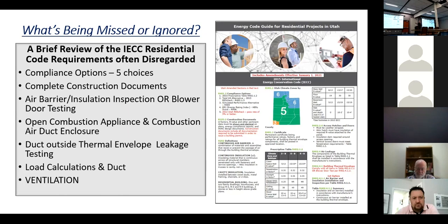Ridge vent doesn't fix it because ridge vent doesn't let a lot of air out. Turtlebacks, an 11-inch turtleback has a free area, by the time they put the screen and everything in it, somewhere around 70 to 90 square inches, which isn't even a square foot. So attic ventilation really compounds the problem. And that's why the number is so broad: 25% or 50% of the load is due to the ducts and air handler in the attic.